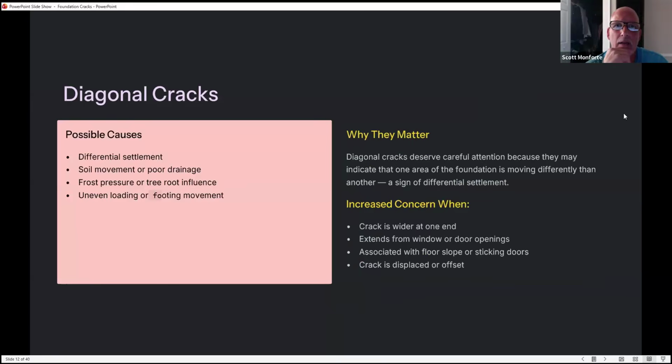So you still have to put a narrative together and explain to people why you're concerned. Well, yeah, if there's a bunch of them, yes, of course, I'm concerned. And to add to that, Stan, even though, Jim, you said there's no indications of seepage, a year later, 2 years, 5 years, they can start to leak. They can open up even wider. Every crack has a potential to leak as far as I'm concerned. If it's below grade or partially below, it could leak. You might see a little staining, efflorescence towards the bottom.